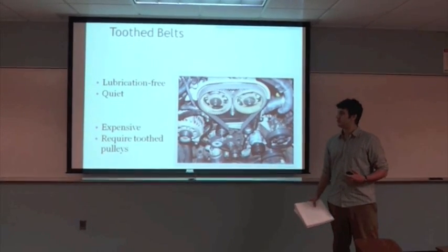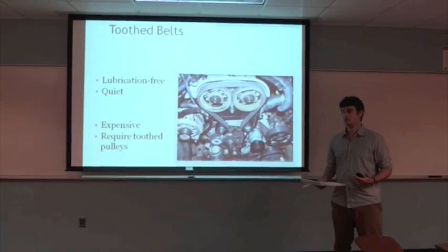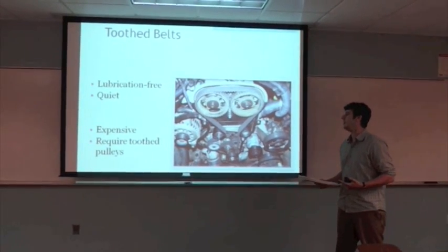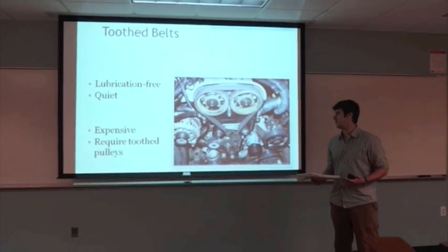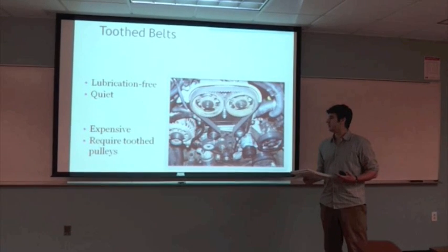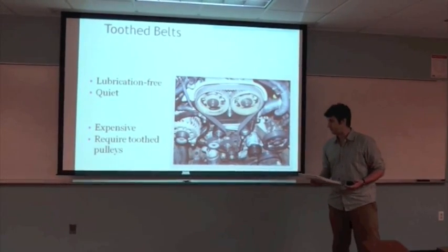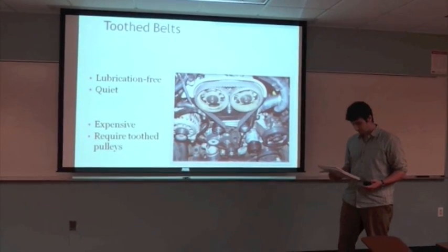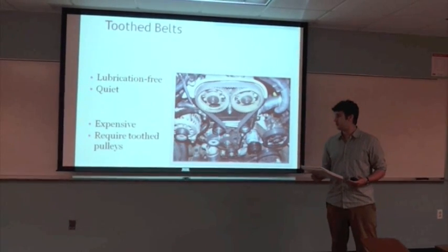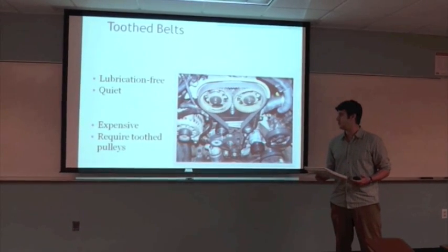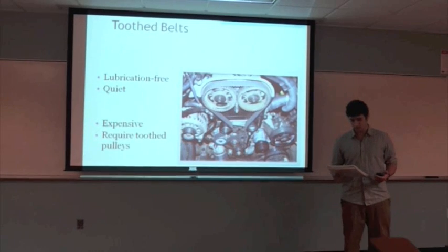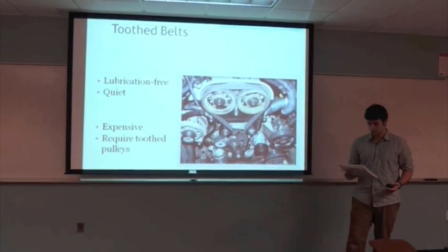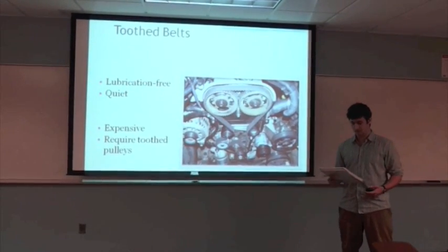Tooth belts are frequently used in a lot of the same applications where you would use a chain. However, you don't need to lubricate them unlike a chain, and they're much quieter. But like I said, they are very expensive. And if you go with the tooth belt, then you also have to go with tooth pulleys, which are more expensive than the regular groove pulleys you would use for other types of drive belts.